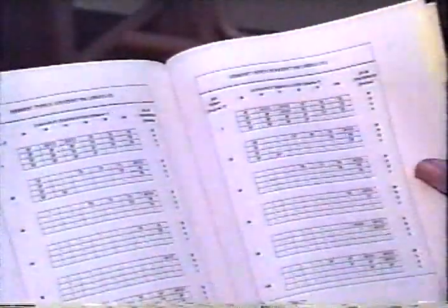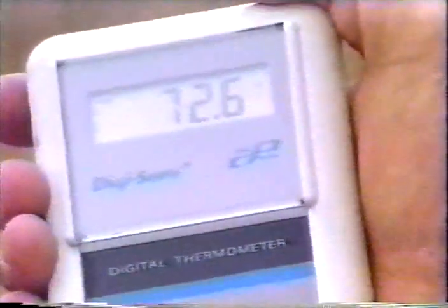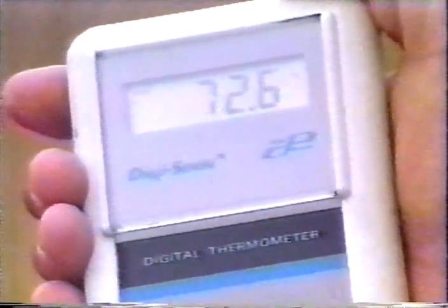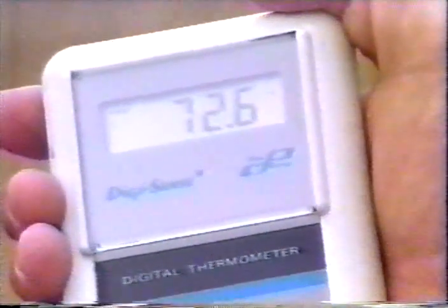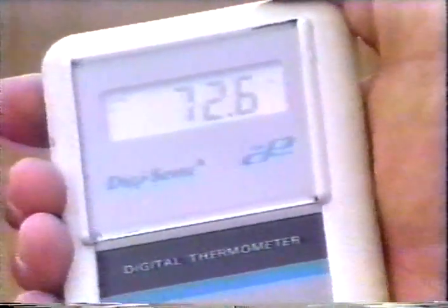Thermal gradients, overheating of concrete, and early freezing of concrete can lead to cracking and loss of strength. Sharp has developed a guide that can be used in evaluating the likelihood of such problems arising in the placement of concrete slabs. The guide contains several tables. Using the tables requires knowing the ambient air and concrete temperatures at the job site.